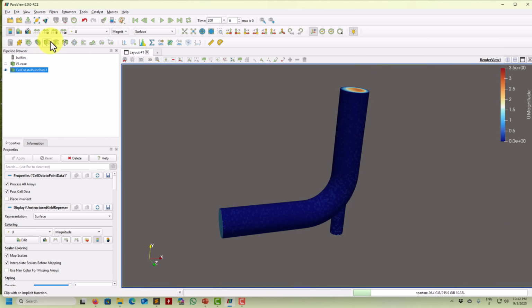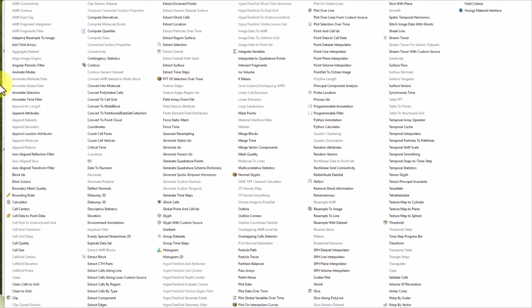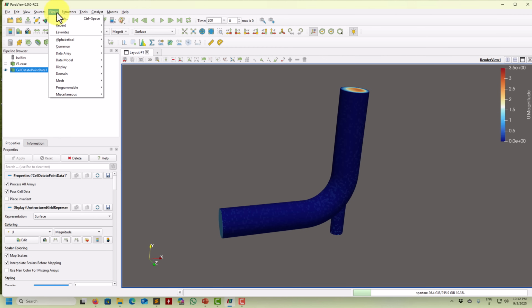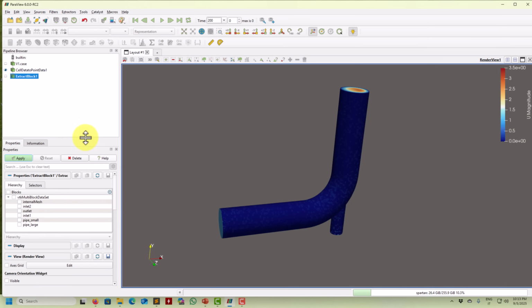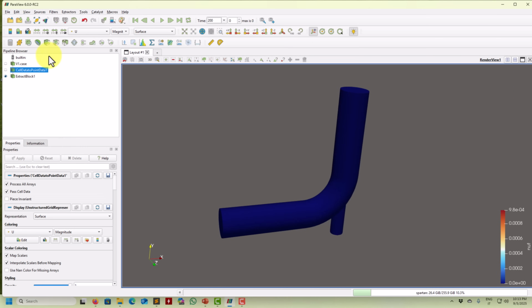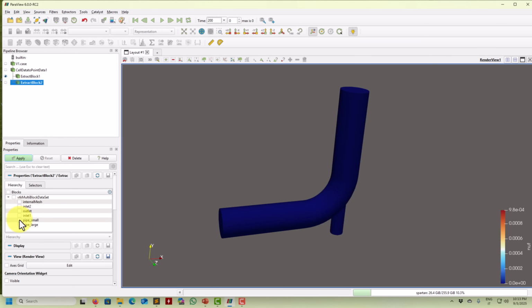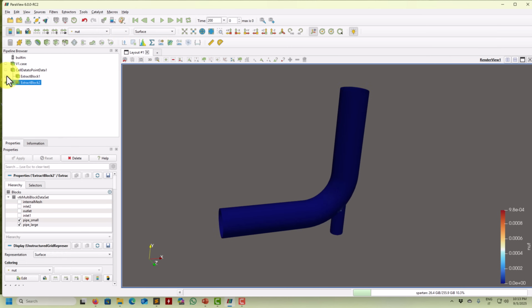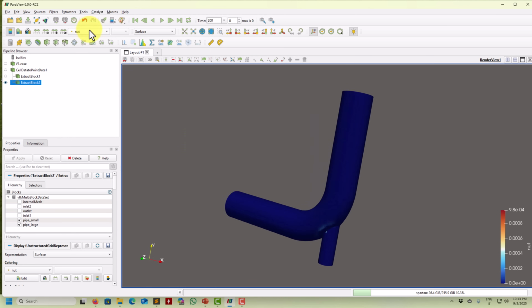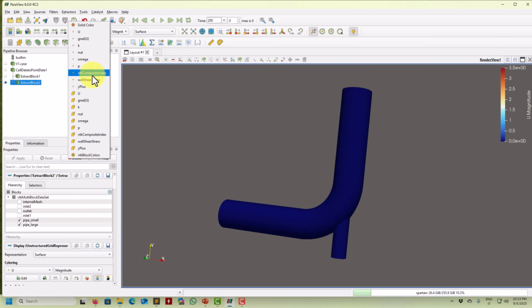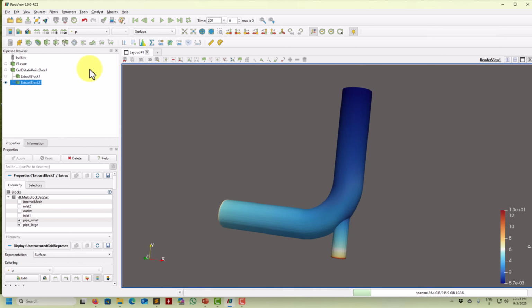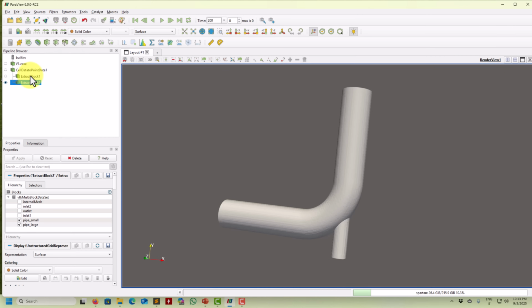Now let me extract blocks, the surfaces, because so far we're reading everything in this data set. I already have it there, but you can go here and find Extract Block, and you select. I will select the internal mesh, I know it is the volume. I reselect this one, and I have it here also. With Extract Block, using this shortcut, I will extract the walls. This is usually how I work. See here that at the walls I don't have velocity. I will show you a trick later, but then you have your pressure and so on. So let me put the color there.